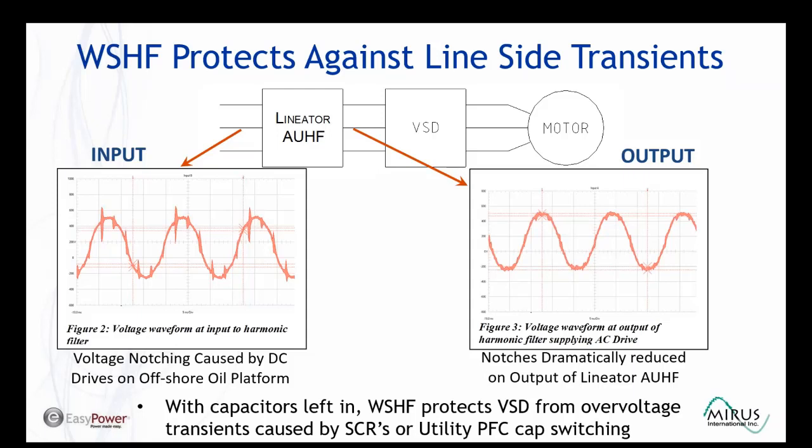So we actually applied our filters in this application, not as much to reduce the harmonics that the drive was generating and introducing back into the power system, but rather to protect the drive from these over voltage transients. Because you can see with the filter connected, the over voltages are removed, and we have much cleaner voltage now being applied to the variable speed drive.